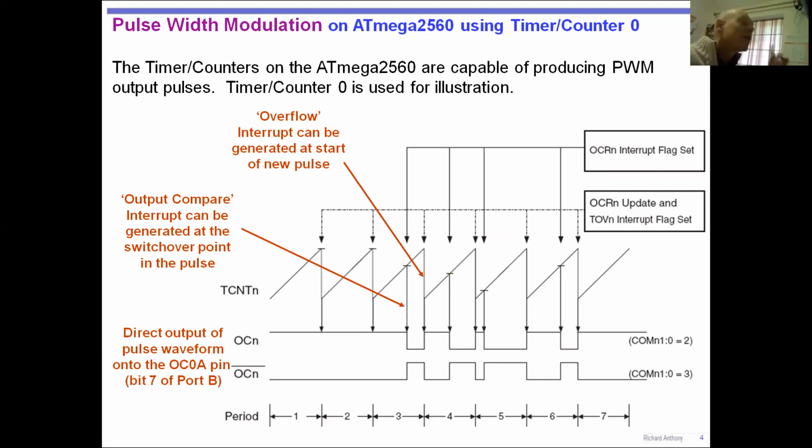Have a look at that code where it says double potentiometers code. That code I showed you in the archive. Look at that code and look at the way the timer is configured, and you will see that I'm using output compare register A and B, or maybe A and C, or B and C, because there are three altogether. I can use any two of those three. It's a very good question. Everyone in the class should have had that same question, really, because I should have explained that and I forgot to explain that point.